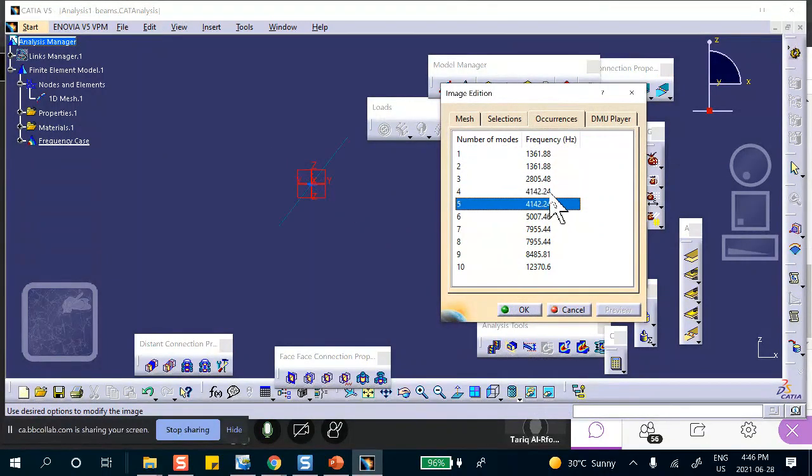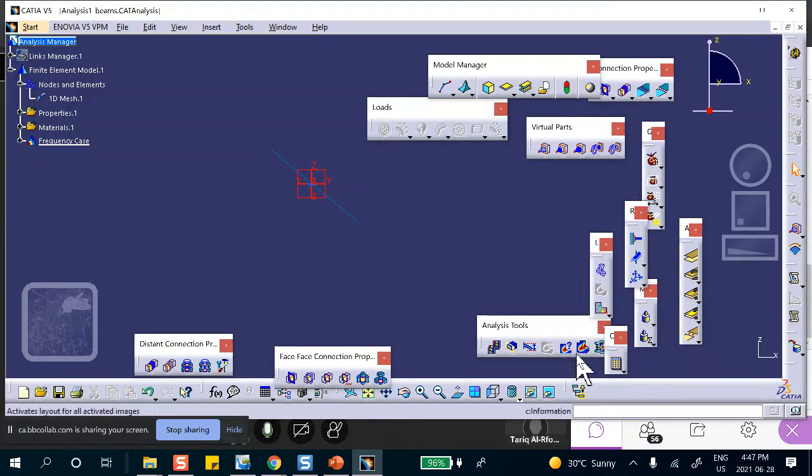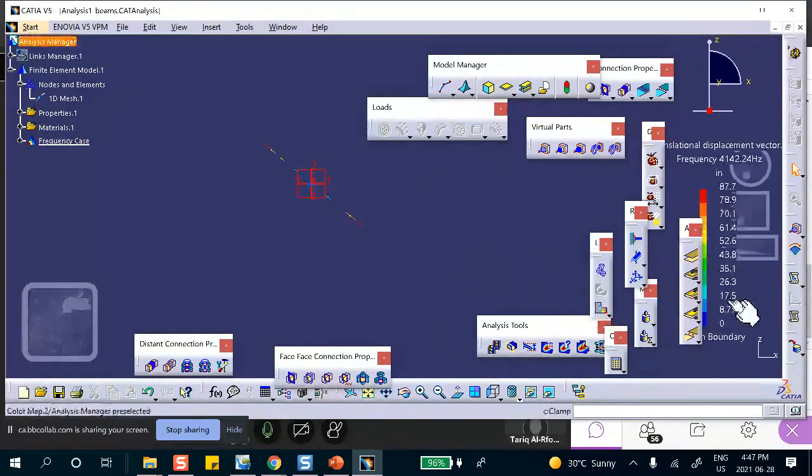Yeah, see, these things are coming in double because if you imagine a beam, it vibrates in, for example, the vibration response in the XZ and YZ is the same because you think about it. Just look at your geometry and look at the restraint. XZ and YZ, there is no distinction between them when you look at the way it's restrained. Okay. Yeah. So anyway, once again, you can plot the displacements. It's totally useless. 87 inches. You obviously in beams you cannot plot stresses, so that's okay.